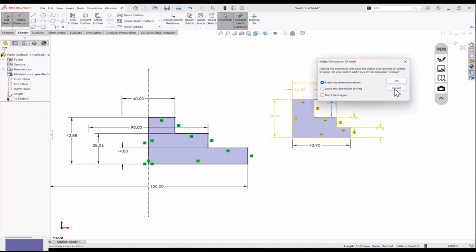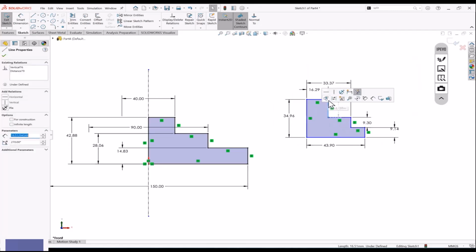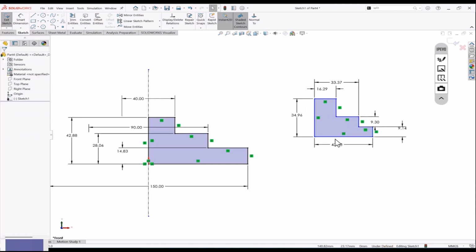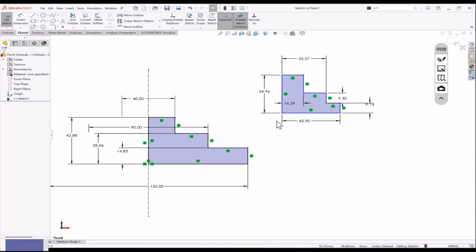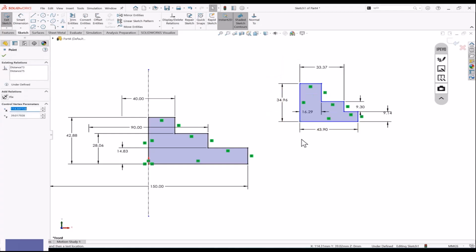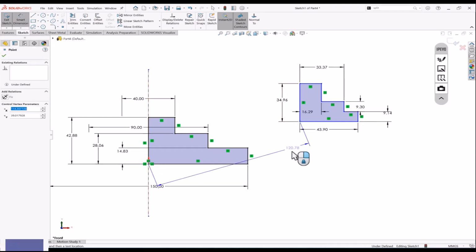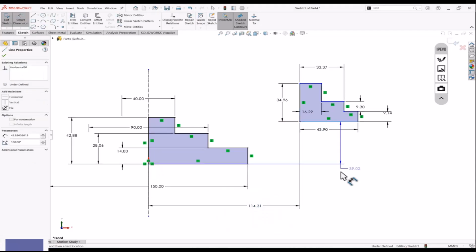So I'll put that dimension also. Now it is okay. Now you see, I cannot vary other things because things are fixed. Sizes are fixed, so size cannot change. But what happened? The object's place is not fixed. The object is defined, but not where it is located. If I want to locate it here only, then I can fix it. But as I mentioned, we have to define it with respect to some fixed thing. If I define it with respect to the origin, you see half becomes black. Again, if I define this, it becomes completely black.